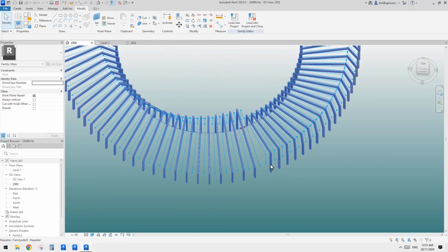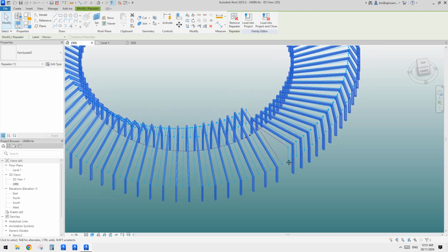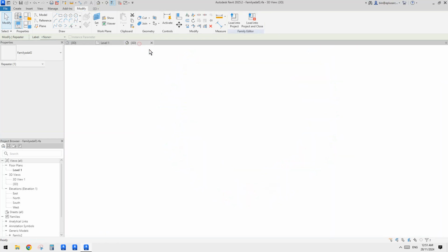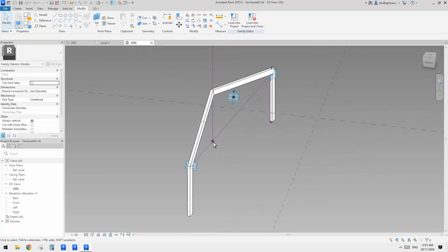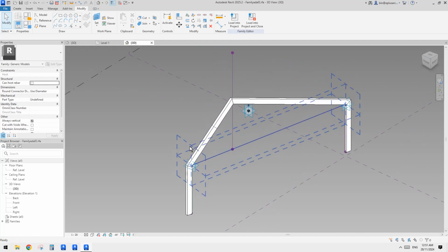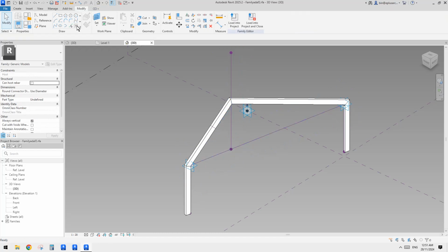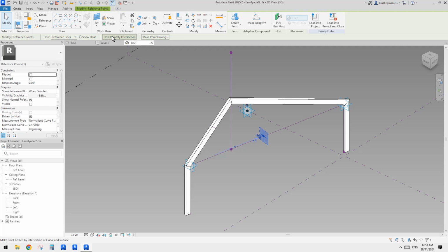And method 3 is we can adjust the family. So what we did is go here and use place a point. Sorry, let me just have a look again. Host point by intersection.